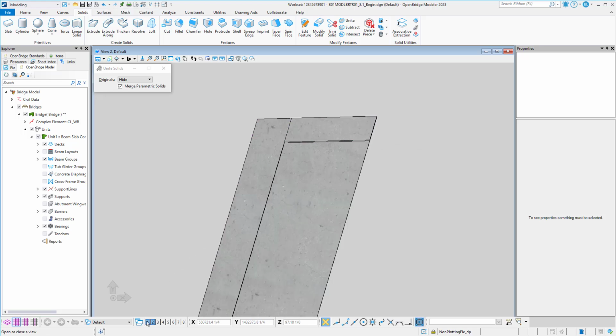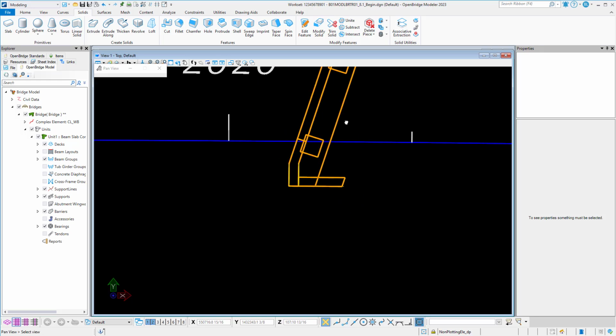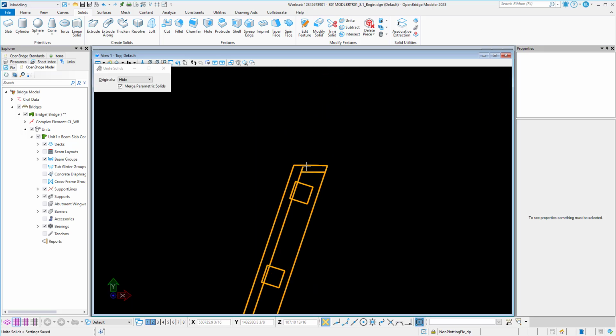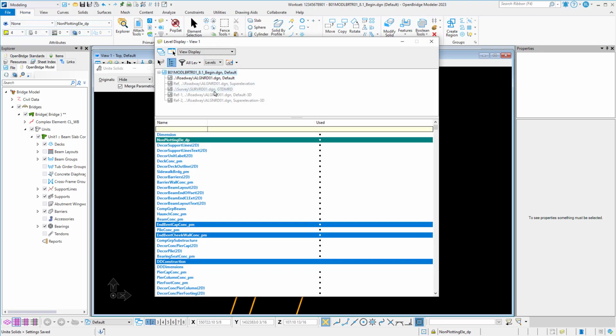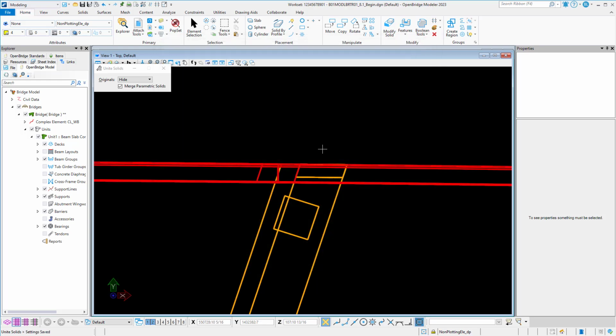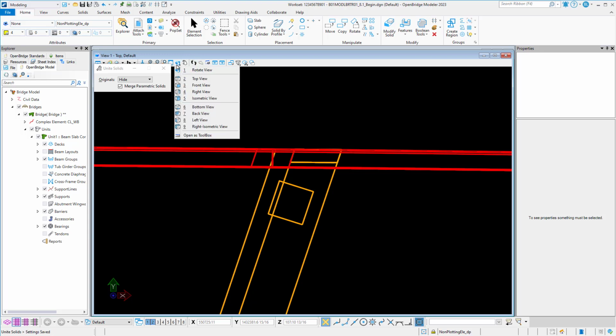Going back to view 1, we will do something similar to the left side of the end vent that we did to the right. We will start by creating 2D lines, making those 2D lines into surfaces, using a surface to then create a 3D chunk, and then from there, trimming and uniting as necessary to get the desired outcome.